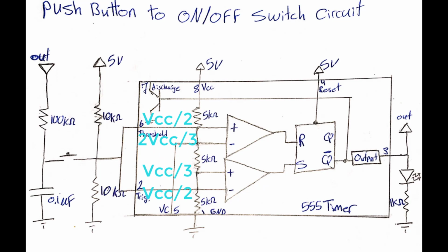According to the comparators' inputs, both comparators will output logic 0, so we will have both set and reset at zero, which will lead Q bar to be logic 1. And the output is inverted, so we have logic 0 at the output. Now let the game begin.